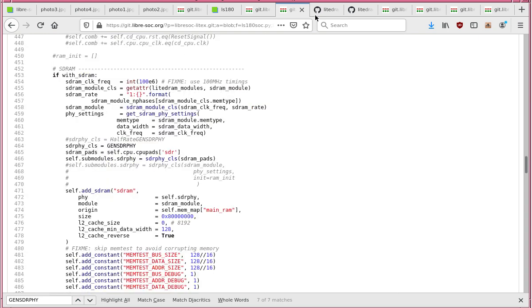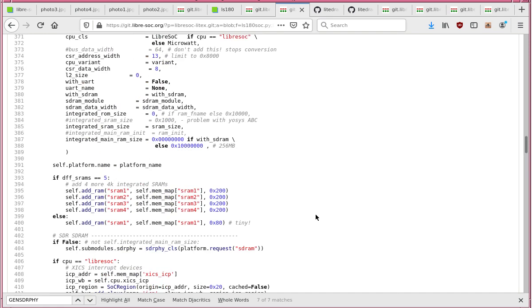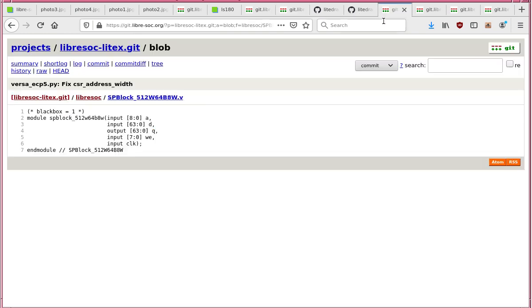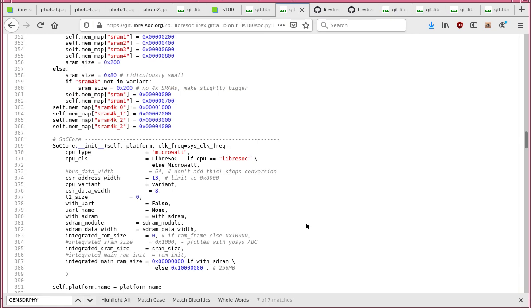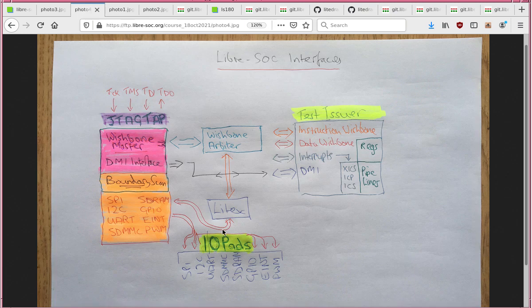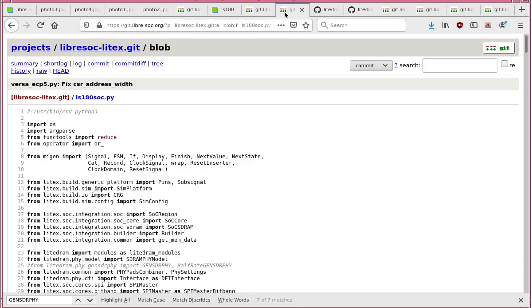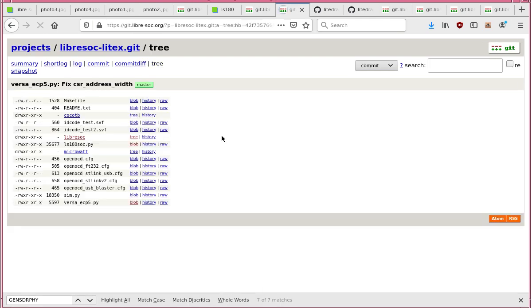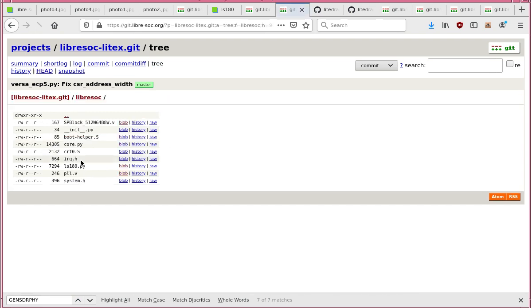Now, here what we also had to do, this is particularly obtuse, is we actually had to have an allocator which duplicated, and that comes back to here. These pin pads inside LiteX, we had to make a separate set and a platform resource, which had one set which we called core, because it went to the core. Ultimately, it went through to the code inside test issuer, and the other one was the standard I/O pads. And let me just track that thing down.